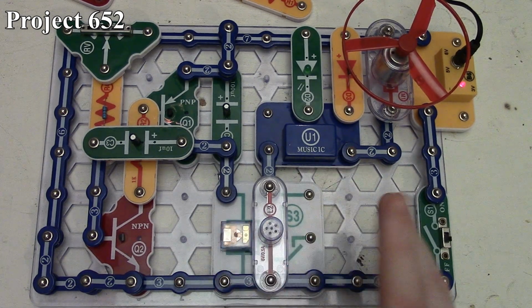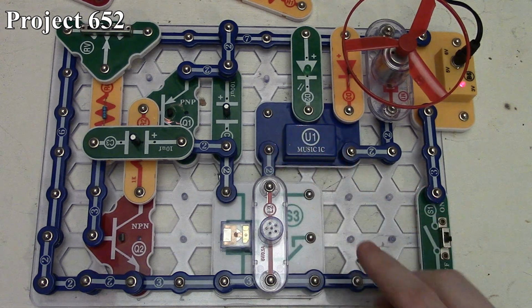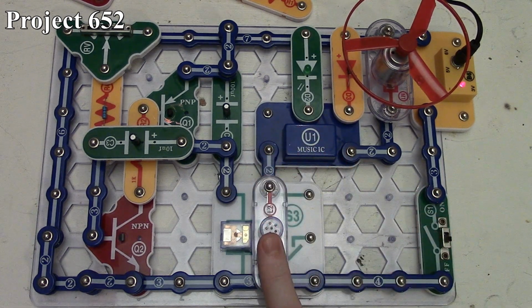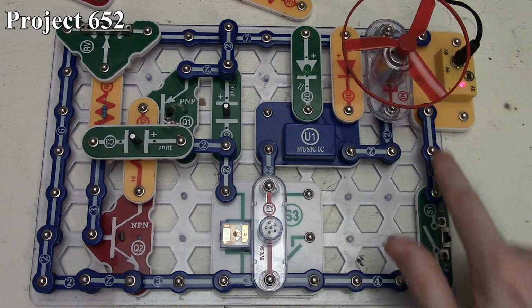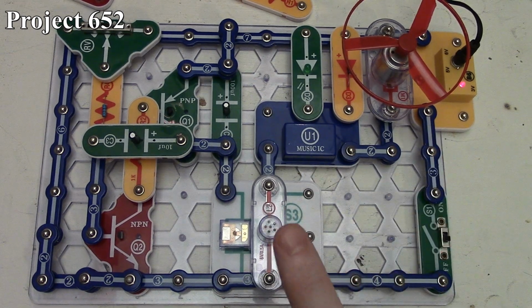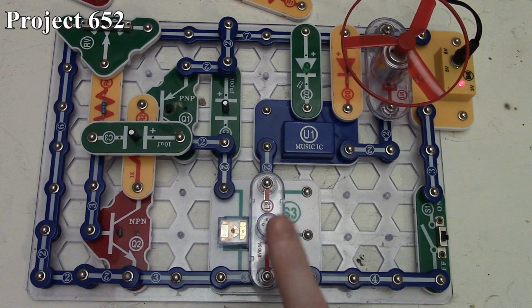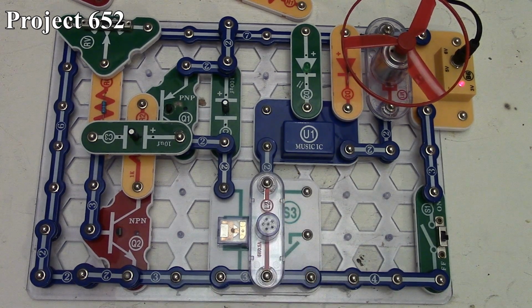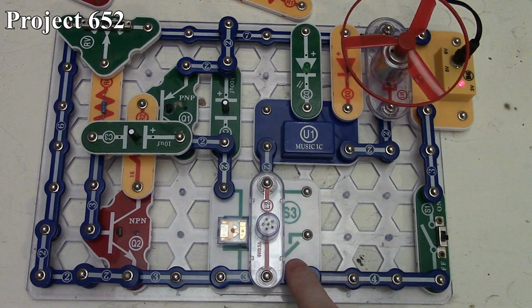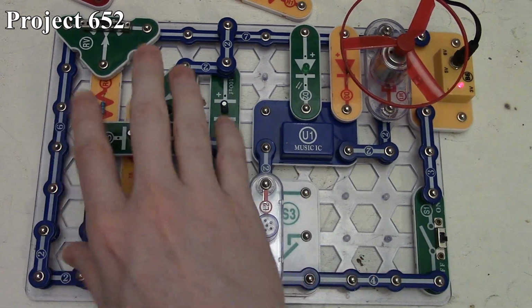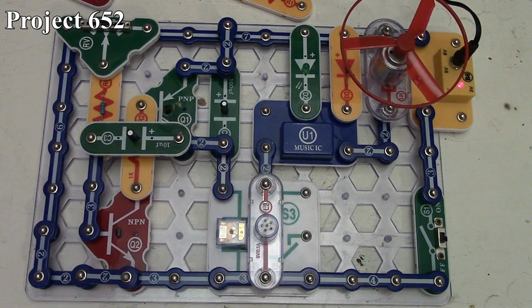And the relay is doing two things. One is that the music IC will normally run through the lamp here. Now I put the 6-volt lamp here instead of the 2.5, 3-volt lamp that it normally calls for. Again, like in the previous project with the alarm IC, I prefer the 6-volt lamp here because we have a 6-volt supply, so that reduces the chance of you accidentally burning out and damaging your 2.5, 3-volt lamp holder. Otherwise you'll have to replace it like I've done before. So the relay basically connects and disconnects the music IC directly to ground, bypassing the lamp here, and then that's all controlled by the oscillating circuit over here.